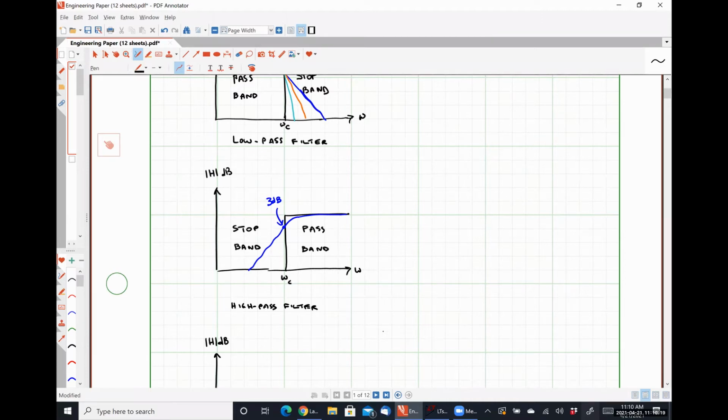The 3 decibel frequency, and we'll get into this maybe in a little bit, is also known as the half power frequency. And so what that means is that if we have a load connected to this, when we're at frequencies less than our cutoff frequency for a high pass filter, less than half of the power is actually delivered to the load. When we're at frequencies above the cutoff frequency, over half of the incident power is actually delivered to the load. So this is a pretty good metric of whether or not whatever you have your filter connected to is actually receiving energy.